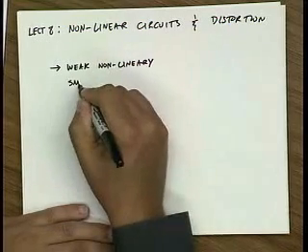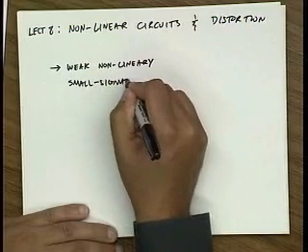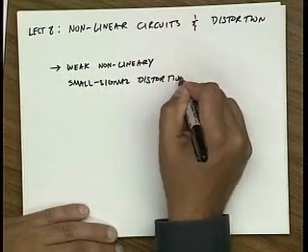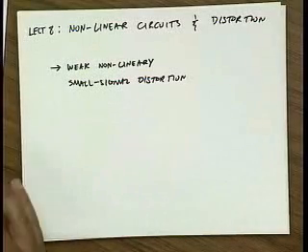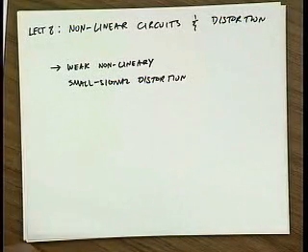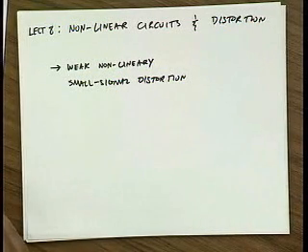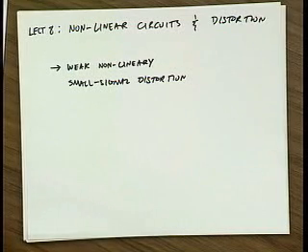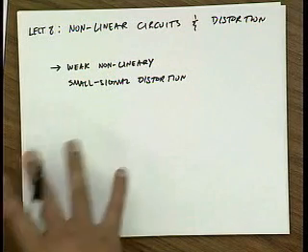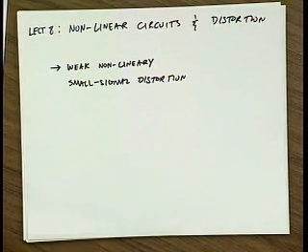Or, if you like, small signal distortion. The idea is that we're driving the amplifiers with relatively small signals, and we're looking at the distortion products, which up to now for linear circuits we completely ignored, but now we see there's going to be some small amount of distortion. When there's a gross amount of distortion, the power series analysis that we do actually doesn't apply. What this power series analysis lets us do is predict at least when the distortion is going to be so gross that it's going to require more sophisticated analysis.